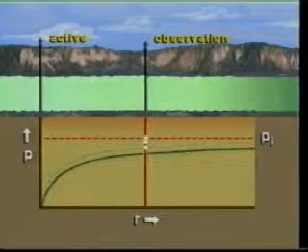The engineer should analyze new wells, whether development or exploratory, in order to determine the potential for sand problems. Existing wells usually have accumulated data that can form the basis for the decision to use sand control methods. The engineer, however, must study the effects of depletion, changing fluid production, both quantity and composition, completion methods, and other variables influencing sand production over the life of any subject well before making the final decision.